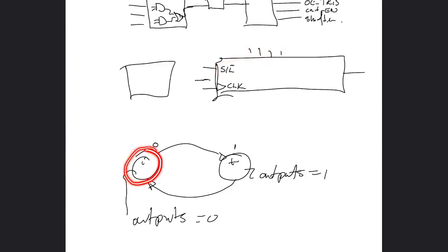So while it's idling, it's drawing in that parallel data, the 4 nibble bits. It's pulling into the flip-flops every single clock edge. And only when we transmit does it stop loading and start shifting out. What I'm trying to say here is you have 3 separate components: the state machine, the shift register, and the counter. And for the counter, we have a control which will be something like count enable.